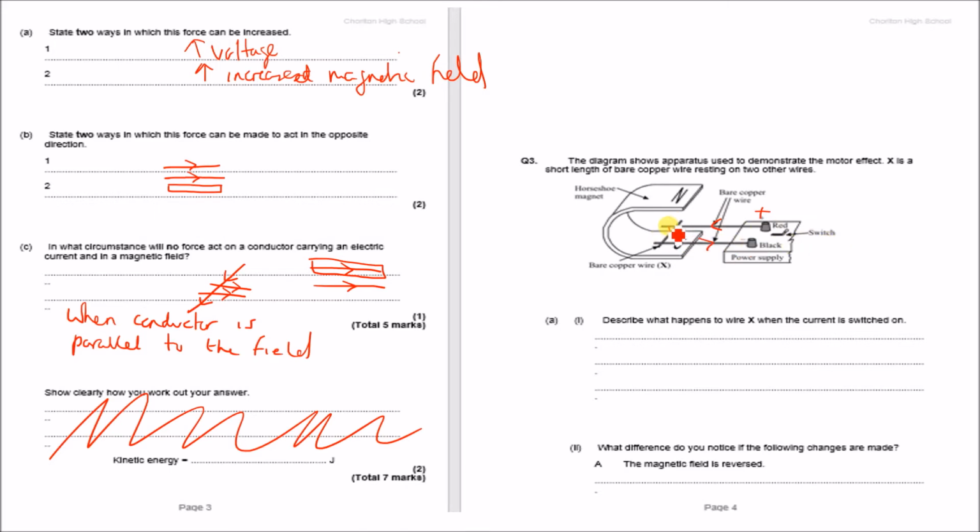So we know going through here the current is coming towards us. So current. The field is going straight down. So I'm going to draw this current again slightly like this, so it's easier to understand that the field is going from north to south like that. So if our first finger points down with the field and our second finger is the current, then we know that the thumb is going to point in this direction. So we're going to get motion to the right.